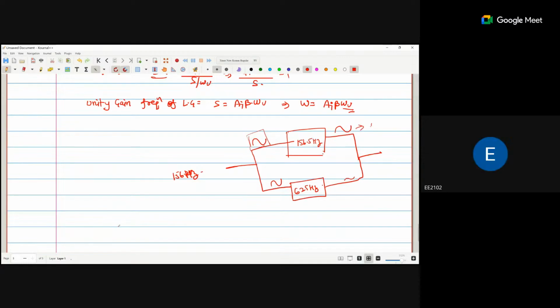Because, for example, this is my sinusoidal signal. Yes, sir. Now if you clip that signal from here and here, you are getting a signal like that. The upper part, yes, sir. Same as the green which I have drawn in blue, sir. Yeah, because that part is clipped, because you are not choosing an appropriate value of resistance and capacitor.